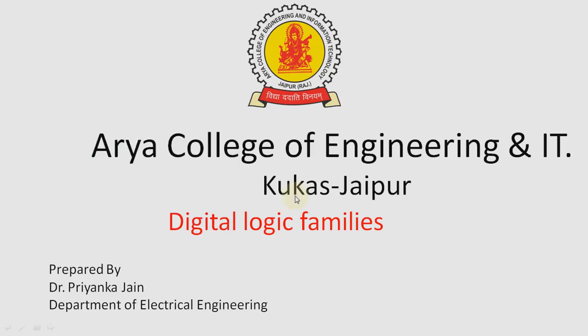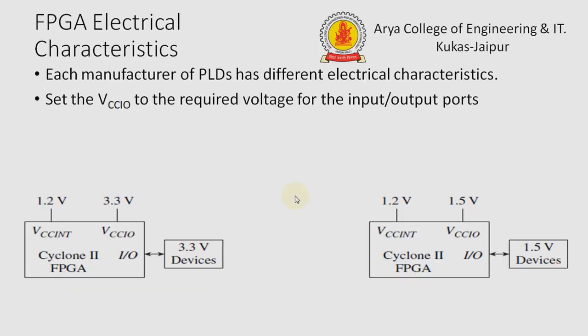Hello students, continuing our lecture series on digital logic families. Now we are coming to the FPGA electrical characteristics of the logic families. Each manufacturer of PLD, that is, programmable logic device, has different electrical characteristics. Set the VCC IO to the required voltage for the input output ports.